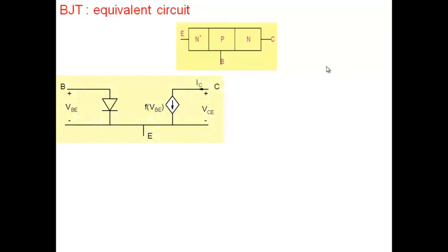So what we had seen is that when we have an NPN bipolar transistor, we can look upon this bipolar transistor in the case where the base-emitter junction is forward biased and the collector-base junction is reverse biased. Of course, the forward biased diode is there between base and emitter. And we also saw that the electrons which are injected from the emitter to the base move on to the collector. So even though the collector-base junction is reverse biased, the collector gets a current here, IC.